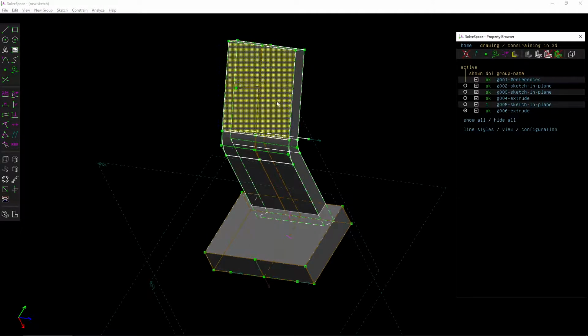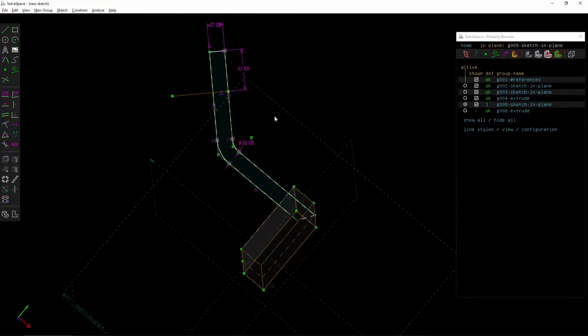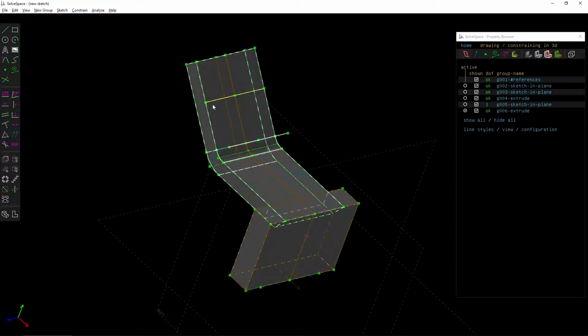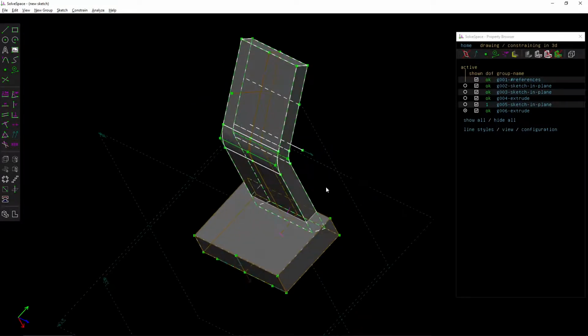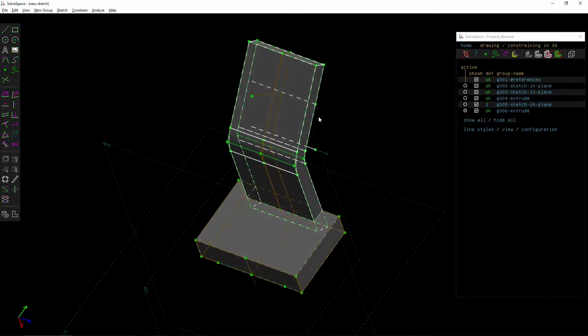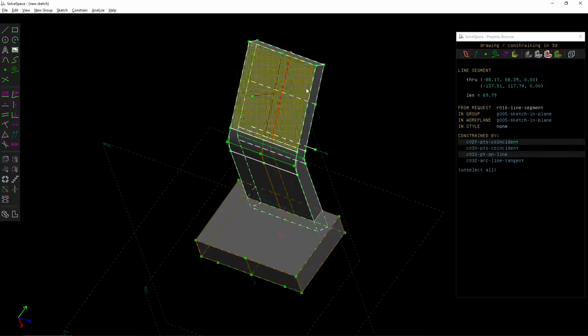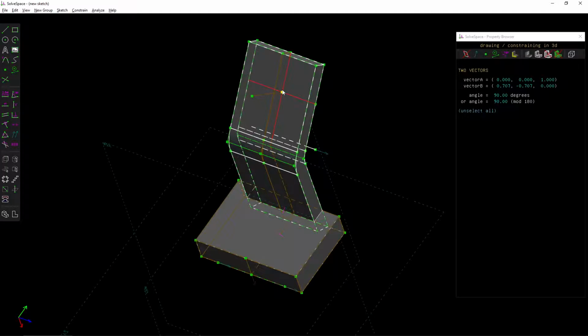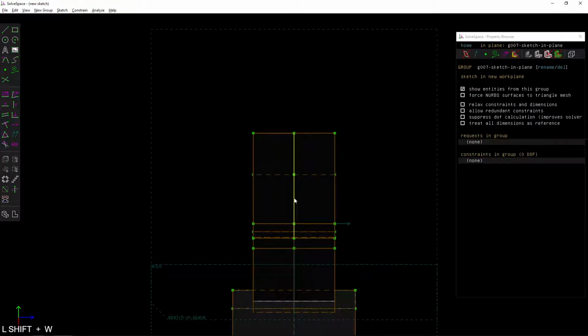Now I want to make the cylinder shape here. It would be good if I have a reference line here, and it's easy to do this. All I have to do is add a datum point on here, and as I soon go back to the extrusion, you see that now I have a line here, which will help me. I want a new work plane, so let's do this. Cylinder 52, I think, yes.